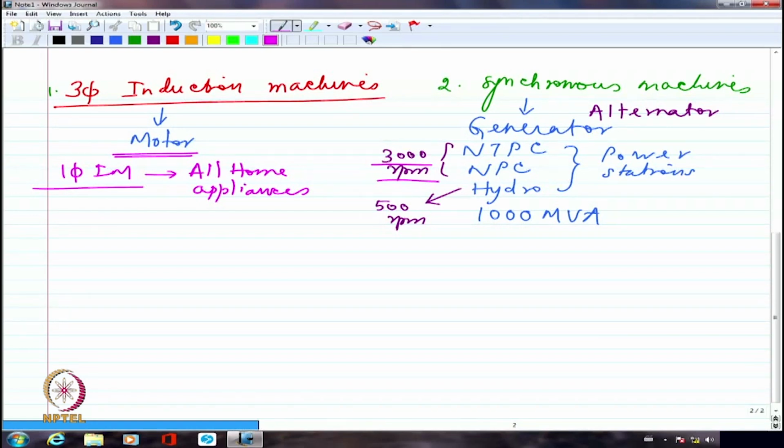But in three-phase induction motors, we have a really good efficiency in most of the cases. It is definitely greater than 85%, if not more than 90%. So for three-phase induction motors, generally the efficiencies are greater than 85%. Whereas in single-phase induction motors, the efficiency is as low as 30 to 40%, nothing more than that. And nobody cares to really improve it either, because it's a very competitive market.